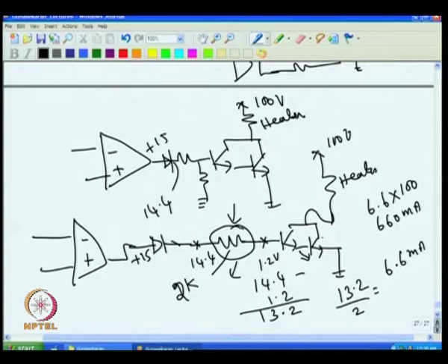This transistor carries the bulk of the huge current, because this will be again multiplied by the beta of this. This big transistor has lower beta. For example, 3055, if I take, the beta is only 20. Smaller transistors have higher beta, that can be even 100. So, if I take this transistor beta as 100, and this as 20, then 660 milliampere multiplied by 20 will give me 13 ampere current can go.